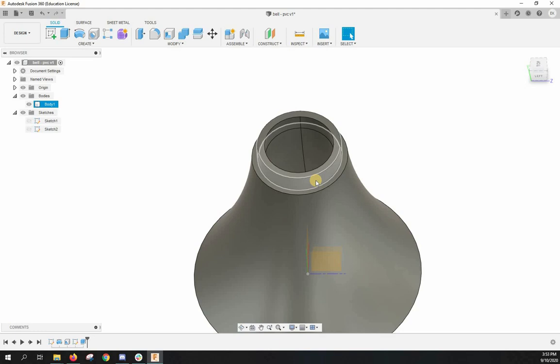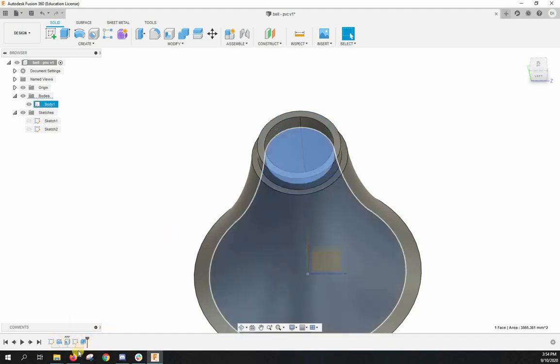So say you needed this to be a little bit smaller. Say you made it too big and it doesn't really fit with the piece that you had before. Instead of creating an extrusion cut where you cut off that tiny bit, you can just go in and change the dimensions. Also notice how when I click on parts, you get these three little hashes there. That shows you what feature you're talking about.